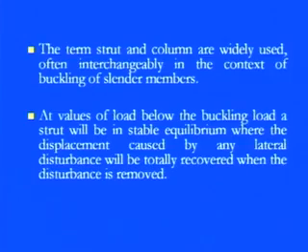So we can say that there is no buckling within that elastic deformation, or this is the statically equilibrium position prior to applying the load, and after the application of load up to the elastic limit. So that's what we are now defining: if the load application is below the buckling load, the strut will be in an equilibrium position, and whatever displacements or deviations are there due to this load application can be regained once we release the load.